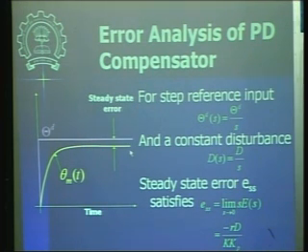So the steady state error in the response curve is represented by this. When you allow sufficient time for things to settle down, the error between your desired position and the actual position is the steady state error. So this is the theta d commanded step response, this is the evolution of theta m with the PD control, and this is finally the steady state error. So we see that there is a finite steady state error when you use PD control.